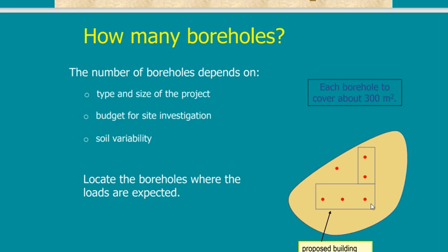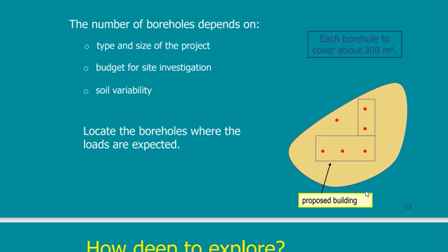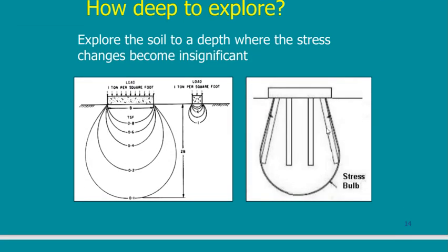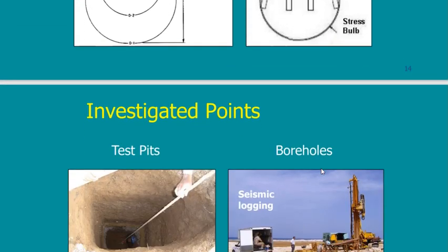As I said before, the soil may differ from one location to the other. I will do lots of boreholes, but I will concentrate my boreholes below the building. And I may take 1 or 2 outside the building just for info, because outside the building I may have a pathway, a small room, security, or other less important structures. So I would concentrate my boreholes below my proposed building. How deep I go is not important for our geology course.